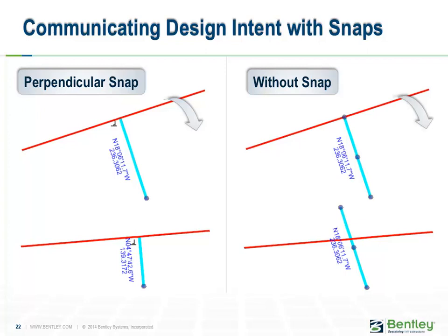The Trim to Element tool will shorten or extend the side road element. This communicates our design intent and is remembered by the software. If the mainline geometry changes, the side road will automatically be shortened or extended to intersect the mainline geometry.